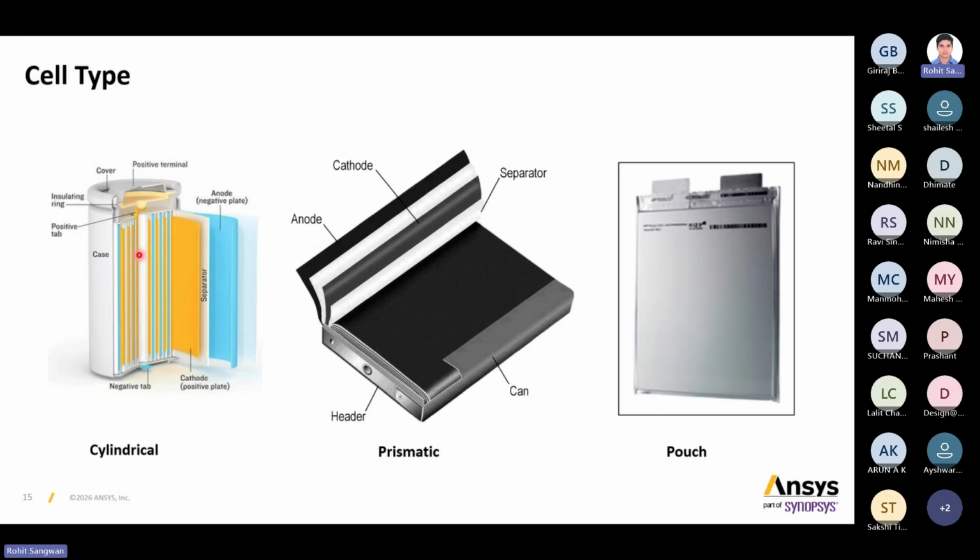So we don't have to create the inner layers. As you can see in this, there are a lot of inner layers. There is a separator. Then we create it in Fluent. What we do, we simply create a complete domain and simulate. We provide some internal heat source, and through that heat source, it will provide the heat. That is the normal conjugate heat transfer method.